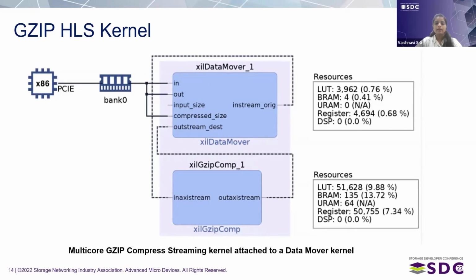There are 8 parallel engines of LZ77, Huffman encoder, etc. inside the GZIP compression kernel, which run simultaneously to improve performance. These kernels are designed in such a way that they can handle multiple compression requests at once in pipeline fashion using a chaining interface. The kernels are also optimized at every layer internally, which makes them an ideal choice for this architecture. The overall resource utilization numbers for this design on the SmartSSD platform are shown to the right.